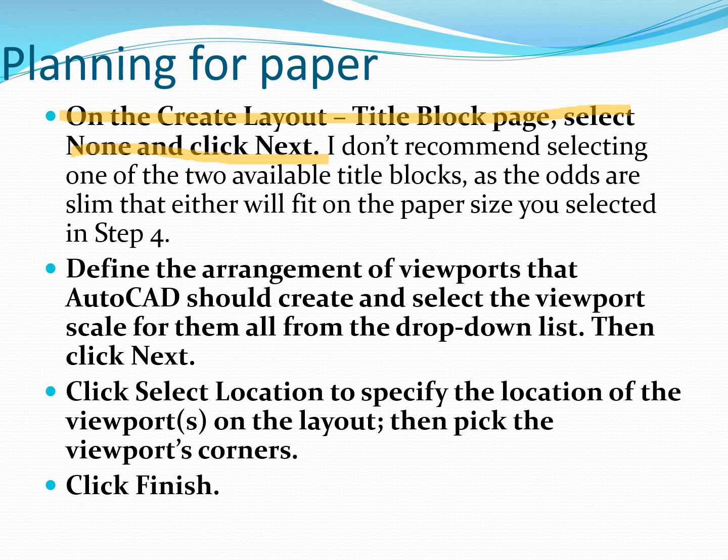Okay, another step is to define the arrangement of the viewports that AutoCAD should create and select the viewport scale for them all from the drop down list, then click next. Then click select location to specify the location of the viewport, pick the viewport corners and then click finish.